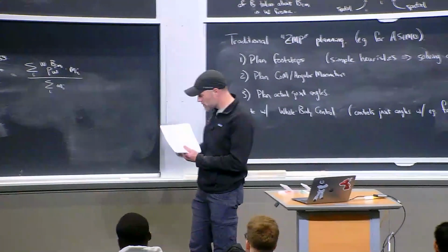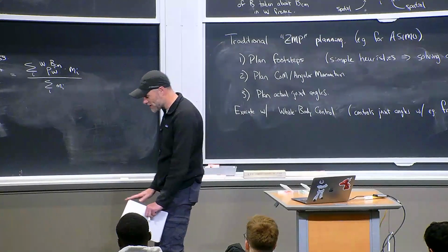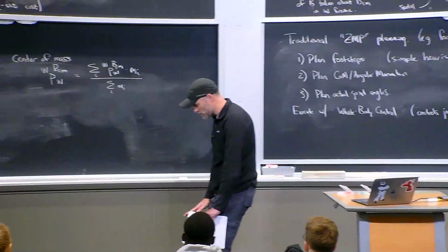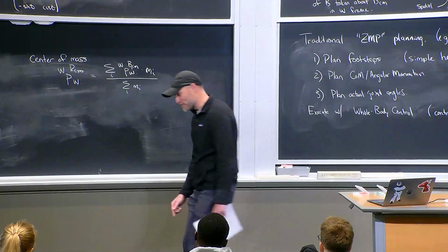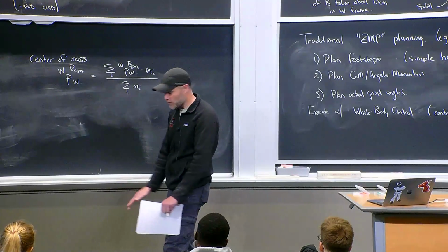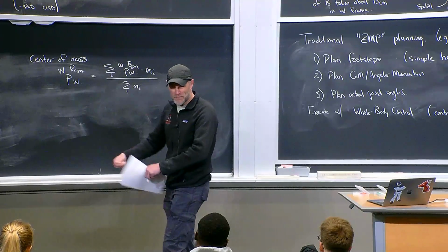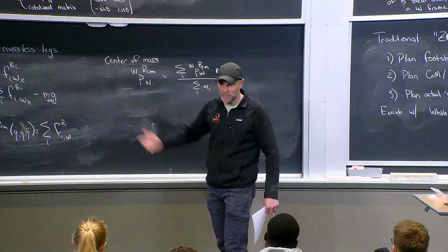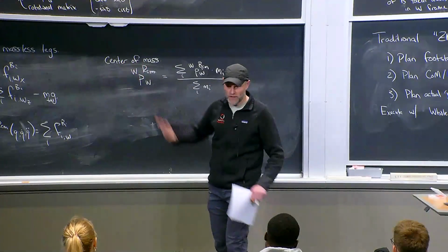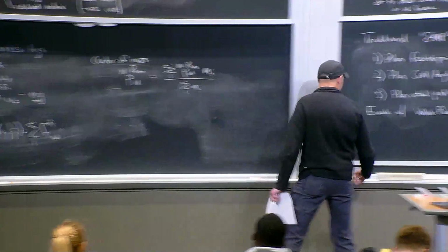Okay, so then, I won't talk too much about the simple version of footstep planning. The simple version would just be, you could imagine a recipe saying, I'm going to move my left foot first, my right foot first. I'm going to move it this far forward. If there's terrain, I'll shift it around. And that very simple, first-thing algorithm you'd write solves a lot of the basic, almost flat problems. And you have to get smarter when you have more constrained environments. Okay, but let's just say I come in with a nominal footstep plan.